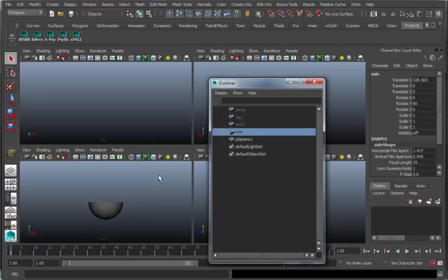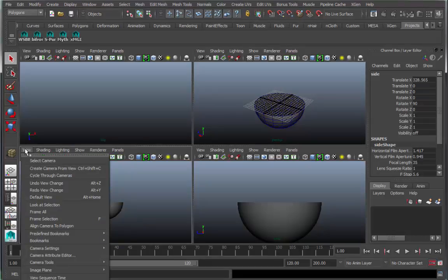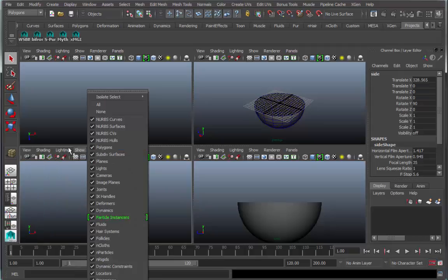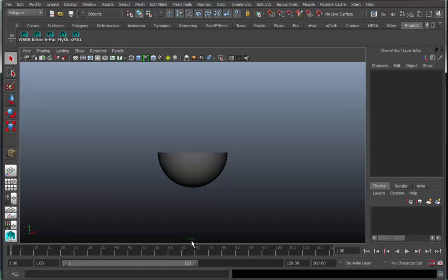However, they do exist in the scene, and the reason we can't see a grid here, and we can here, is the camera may be too close to the sphere. Now there's two different concerns here. One is that Maya is only going to draw so many things within its view camera, and the user dictates what that view camera is. Within each modeling window, there's a separate series of menus, the modeling window menus. So for the time being, let's just concentrate on the front camera.